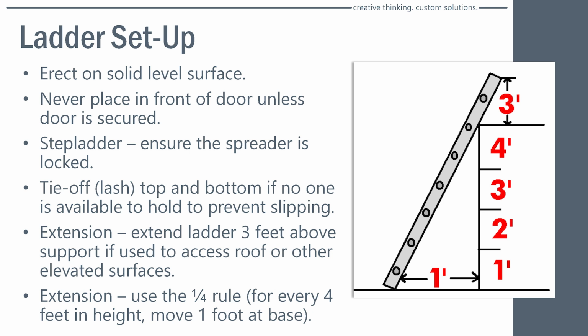We recommend, too, that you secure that ladder somehow or another. Like when you're going up it, does somebody hold it for you till you get to the top so it can be tied off, or secured? Notice the 3 feet at the top. That gives you something to hold on to. I know deer season is coming up before too long, and I've seen a lot of deer stands where the ladder goes up and just stops at the floor.